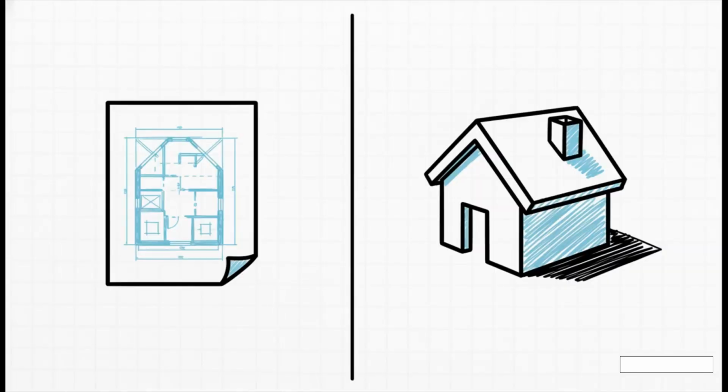And this brilliantly illustrates the unifying golden rule that unlocks the logic behind every single ratio we've talked about today. It is always, universally, drawing size on the left, real object size on the right. Always. Whether you're looking at 50 to 1, 1 to 1, or 1 to 10,000, that formula is totally unbreakable. The left side is always the paper, the right side is always reality.